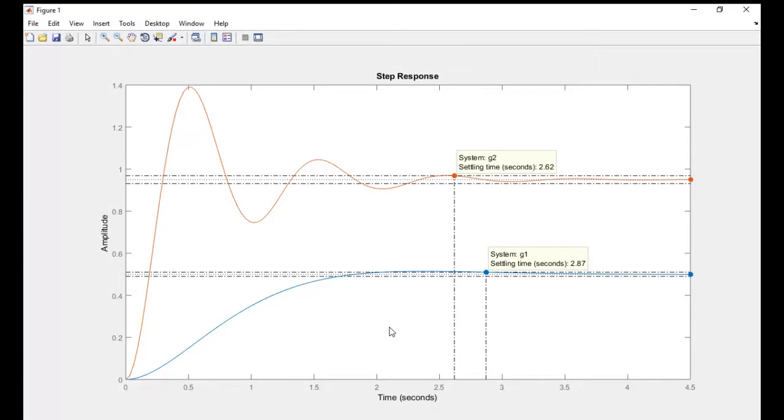I don't know if this is relevant, but I realize that there's an overshoot. The peak amplitude increases. You would want, let's go back to the drone example. You have a drone and you put a load onto it, or, in fact, this wasn't a load situation. This was a step input. So let's say you have a drone and you provide a command to the drone to move from altitude, say 1 meter, to altitude 2 meters, and then your drone starts to do something like this. Would you want that? By the way, what would the drone be doing based on the red plot?